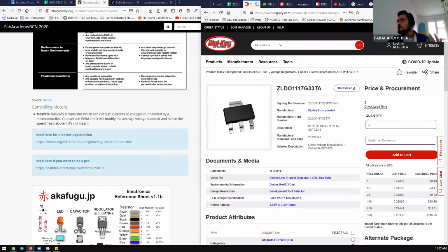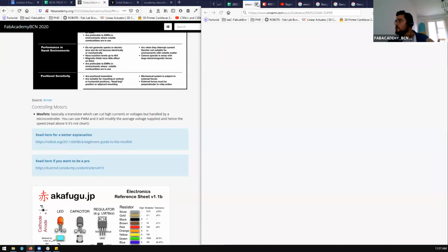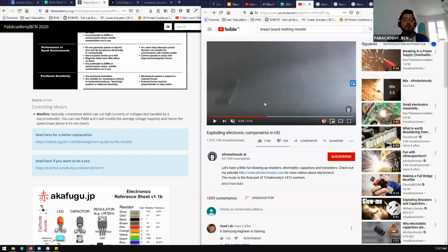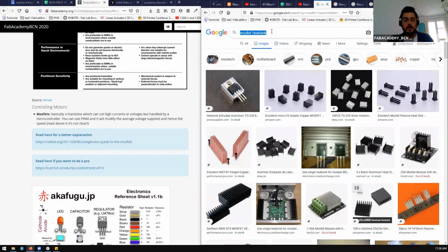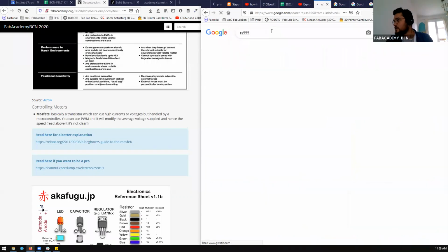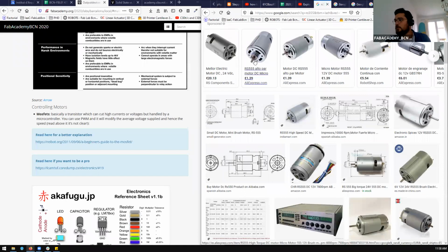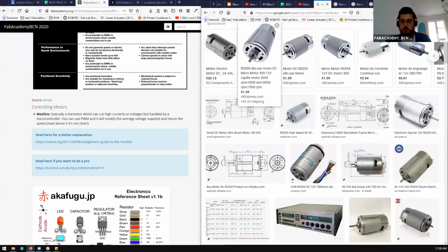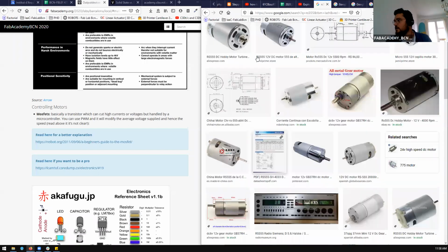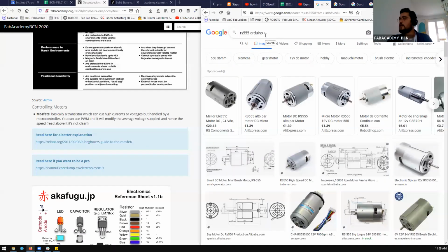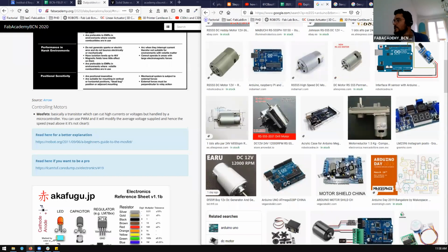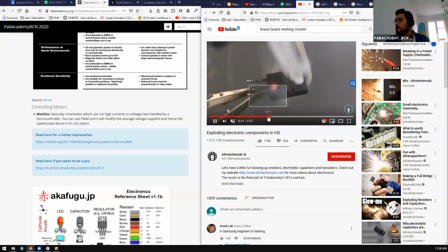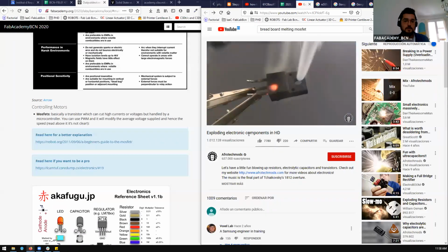This is when you use small currents. So let's close this part. What happens if you don't do this and you run, for example, a medium-sized motor? A motor like this is a really standard one. It's a DC motor, more or less big, the one that you might use for a small airplane or something like this. If you run them with a TO-220 MOSFET, which is something really standard, this might happen if you don't use a heatsink. And it's really common to see this.